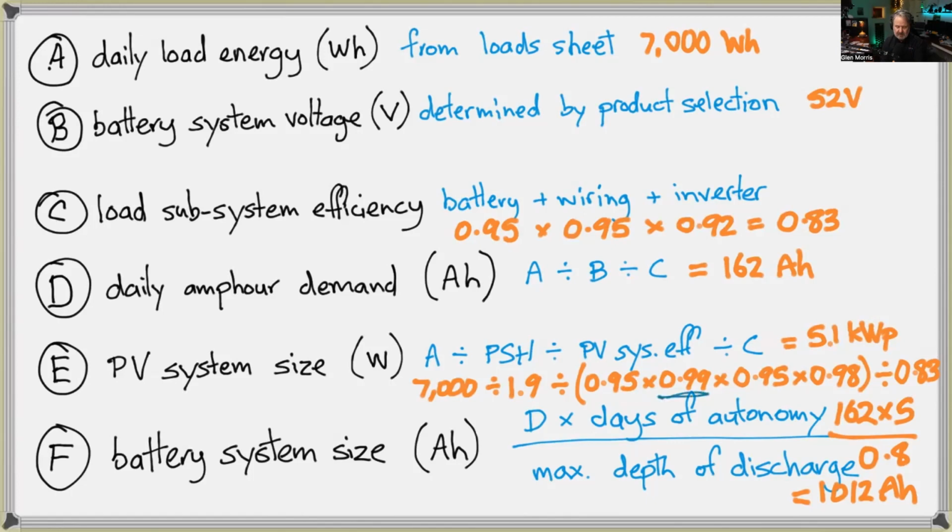The next number is how much have I lost transmitting that power from the panel to my solar inverter or charge controller? I had to transmit it, as in connect a wire to it, and so it's lost some of the energy on that wire. And that wiring loss I'm putting down as 1%. Now, these days, with relatively high voltage strings, we often run our panels at 300, 400, 500 volts or so. There's very little loss because of the high voltage, low current. It's current that causes the losses, all the cable size with respect to the current. So 1% loss is very doable for cable.